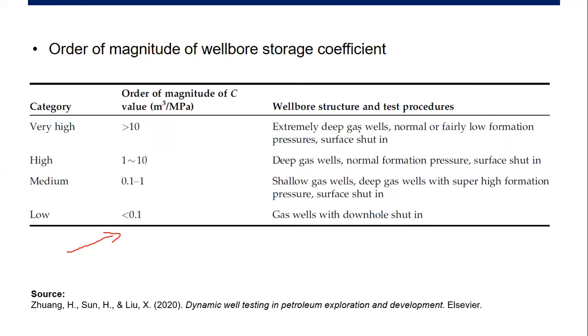Wellbore structure and test procedure in this condition: usually we find it in wells which are extremely deep, and then normal or fairly low formation pressure and surface shut-in. So if we perform surface shut-in, usually we find very high wellbore storage.